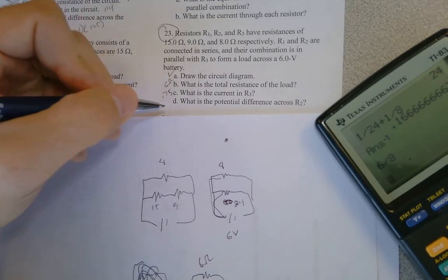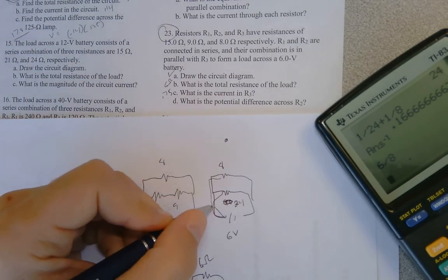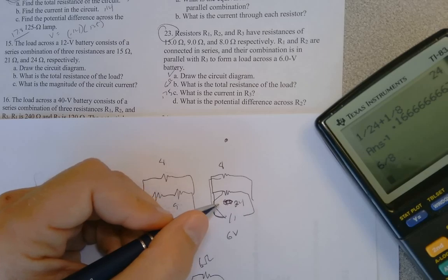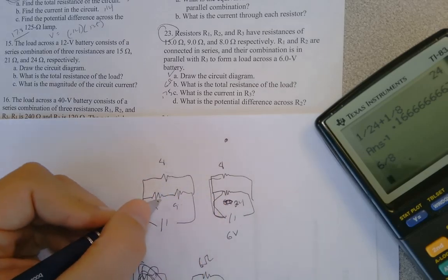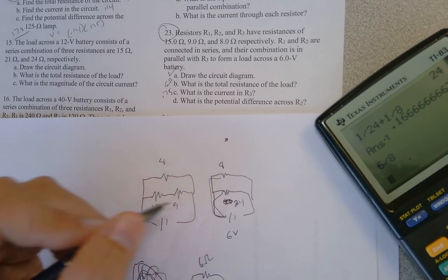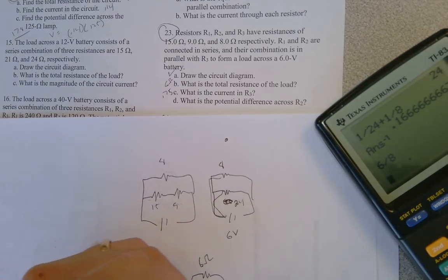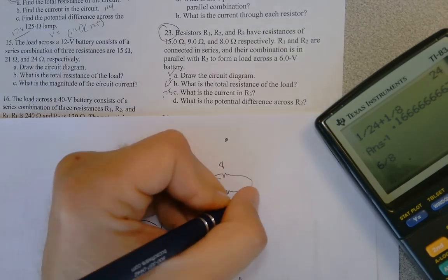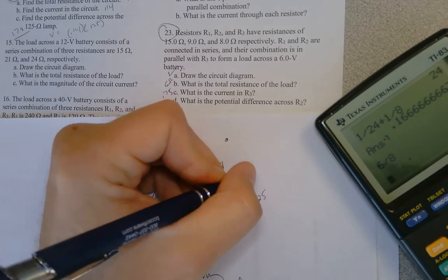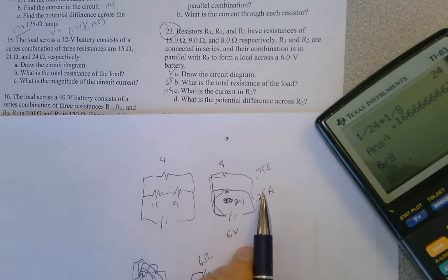What is the potential difference across R2? Well, this one we're going to have to work a little harder at getting because here I'm going to need to know because the whole voltage will get spent here, but some of it here and some of it here kind of thing. So it'd be helpful to know what the current is there. So the total current is 1 amp. So that means that across this one, we get 0.25 amps because this one got 0.75 amps, right? So we've got our 2 amperages there. So then we go